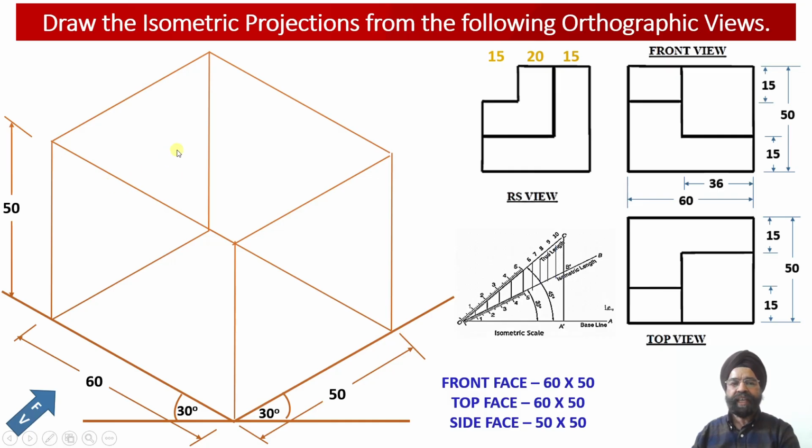So one vertical web we are going to encounter towards this portion of the solid, and this vertical web will be changing direction over here. So this way towards the back side there is going to be a continuous web, and from the horizontal side there will be one web over here. So let us start construction of this particular engineering object in the isometric projection.